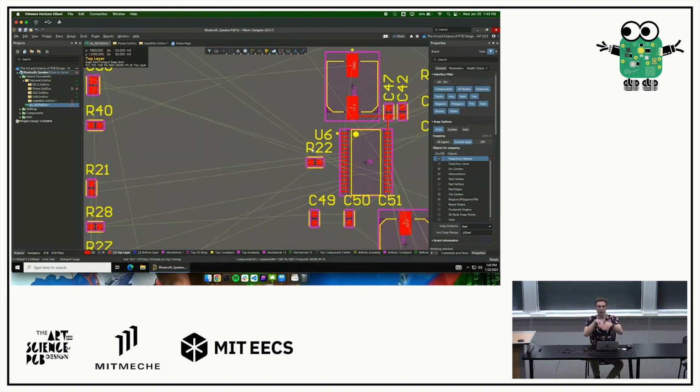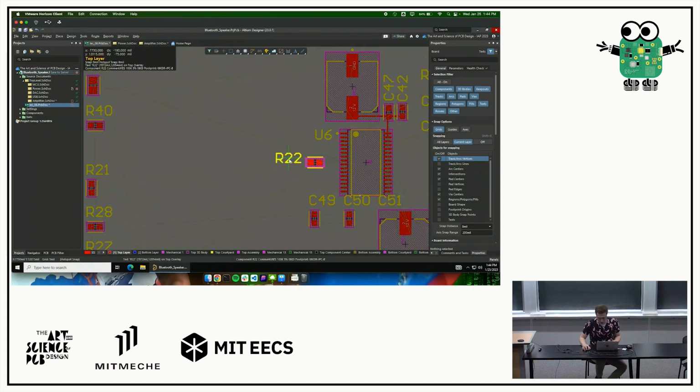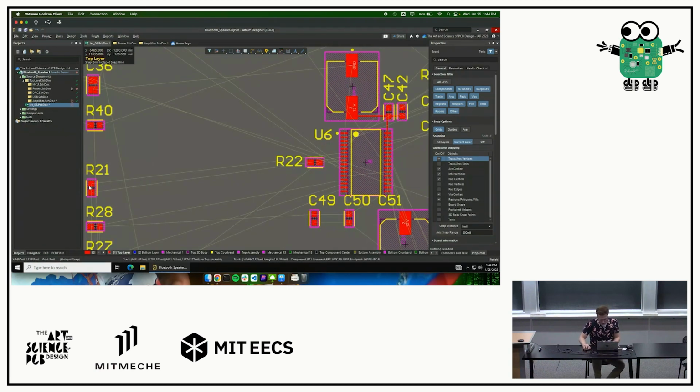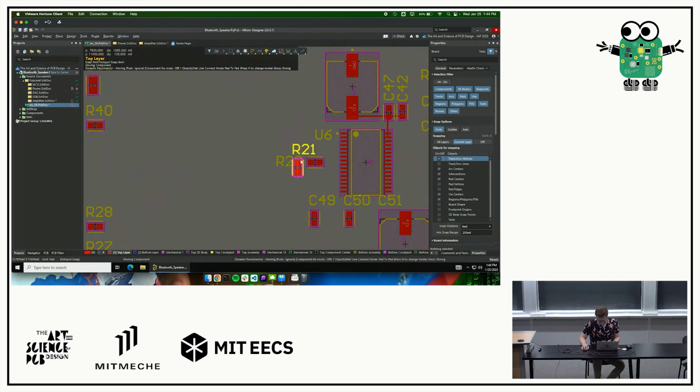And maybe we try and park all the parts in the side of it. Okay, I'll drag the text over here so that we have some space to work. But let's grab another part. Okay, given that our air wires are like this, should this go on the top or the bottom of R22? Top or bottom? Top, right? Because if we zoom in,